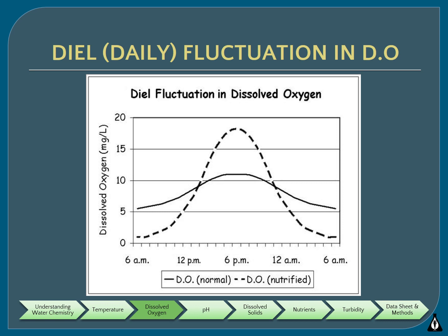If the previously mentioned factors result in a large dip in dissolved oxygen at night, you might have problems first thing in the morning. You can see on the graph where the dissolved oxygen levels at 6 a.m. are below 5 milligrams per liter and within lethal limits for aquatic life. In other words, organisms that require oxygen could begin to die if the dissolved oxygen drops below 5 milligrams per liter in a stream. This is especially true if the night is followed by a cloudy day.